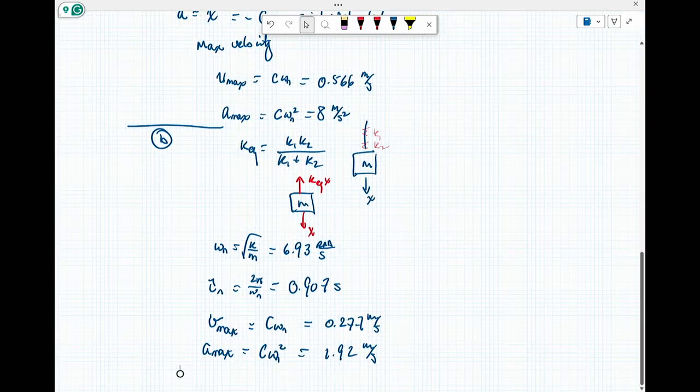And you'll notice I'm not really doing any type of analysis. I'm putting in all of the free body diagrams and just putting in the results. So once I have this, I can write that. I don't even have to write m x double dot plus kx or minus kx is equal to 0. No, it's plus kx, or minus kx, that's right. So I have the downward direction as positive x. But in the end, all I'm going to do is just write omega n equals square root of k over m.